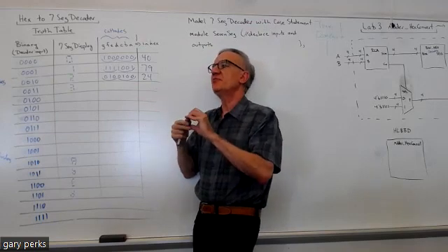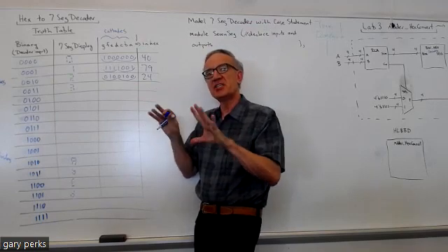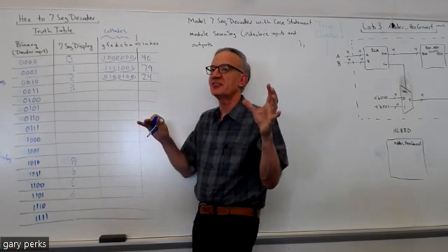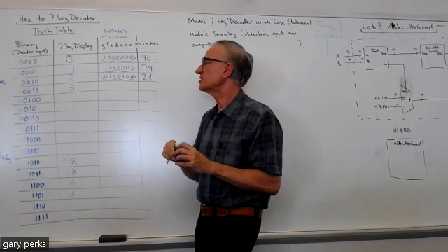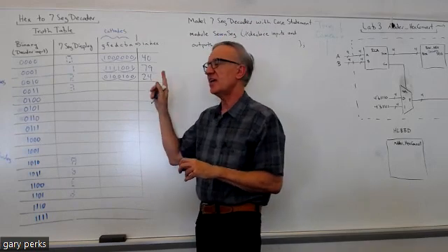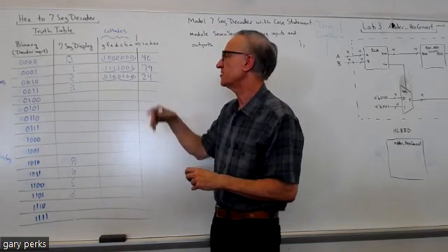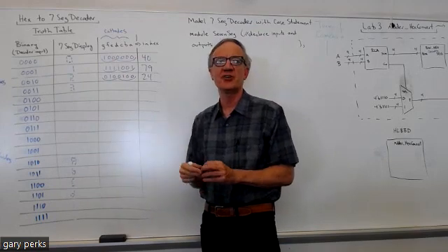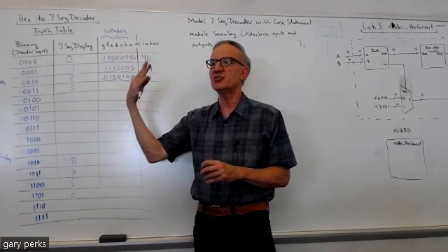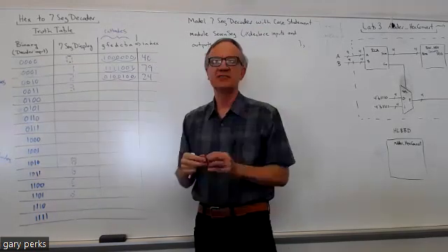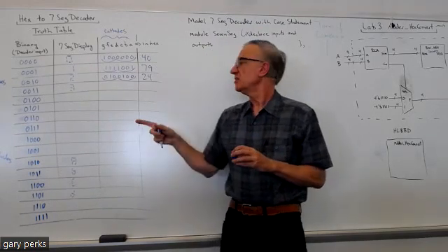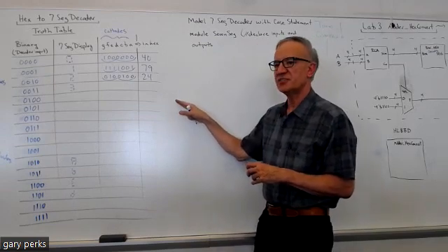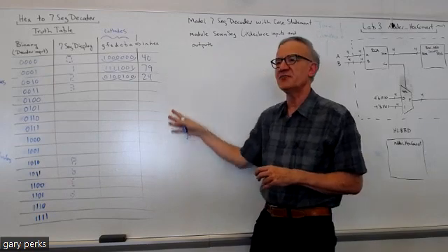for lab 3, provided that you have your MUX all simulated and working correctly, because if you don't have your MUX simulated and working correctly, that's where you want to start, okay? But if you have your MUX simulating correctly, today, once the activity is over, the lecture and activity, this is where you would start. You would want to fill out this truth table for all 16 rows. Okay, because you're going to need this when you model your decoder. Okay? So before we move on, any questions up to this point? Does everybody feel confident they can fill out this table?